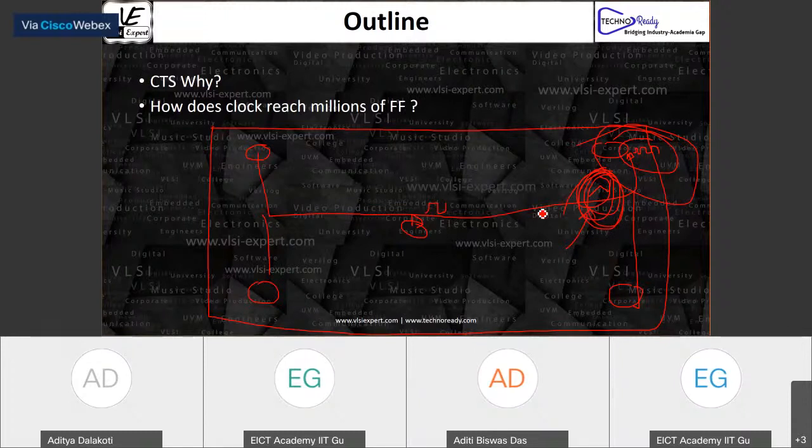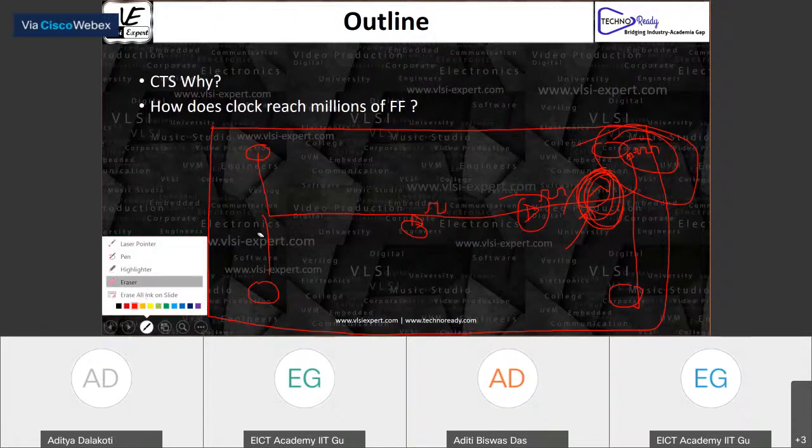So then what you do is you say, I put a buffer here again. That will clean up the signal a little bit. And now the question is, how much do you want to clean up here? Just enough that your noise doesn't affect you, right? Because if you put a buffer just before your flip-flop, then you'll still have a nice transition. But in order for the jitter to not build up, you just care about powering it barely enough. So this is the whole trade-off space of clock tree synthesis, which has to be understood before you actually go and do a clock tree synthesis.